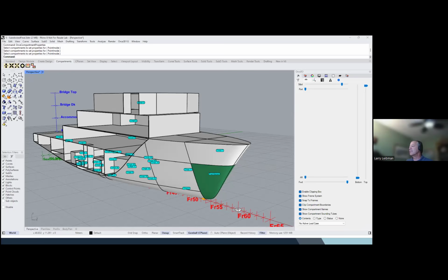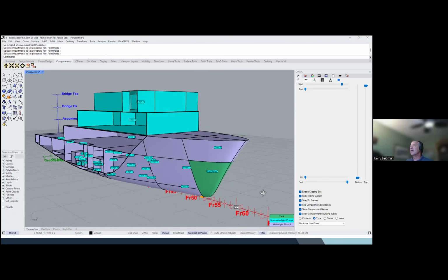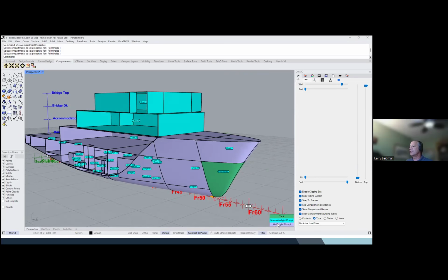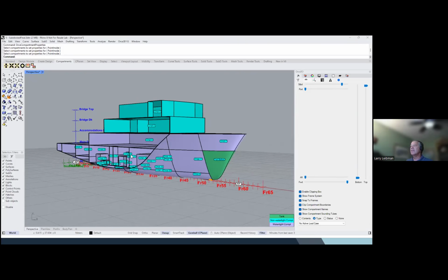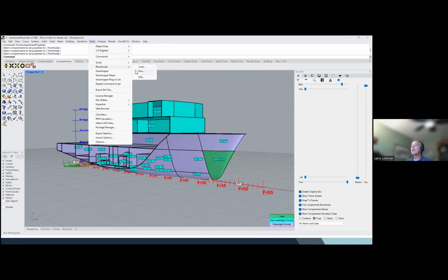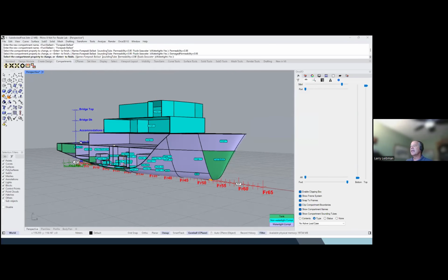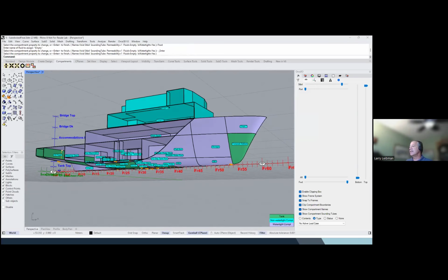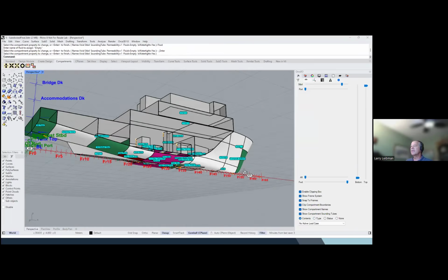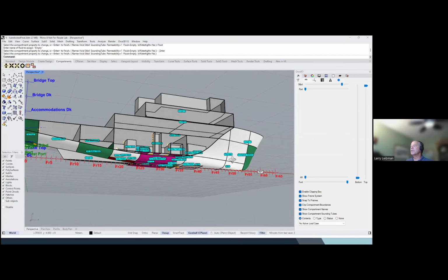There is an option to display, down here in the View tab, compartments by their type. So we show non-watertight compartments in the cyan color, and tanks in green, and so forth. Okay, so you can go through that process of naming and assigning properties. And again, I have a script here that I'm going to run real quick that does all of this, so we don't have to sit here and wait for me to do it. And basically, again, showing the scriptable capability of these commands. And you can see how it's gone and set different tanks with different contents and different compartments with different names.